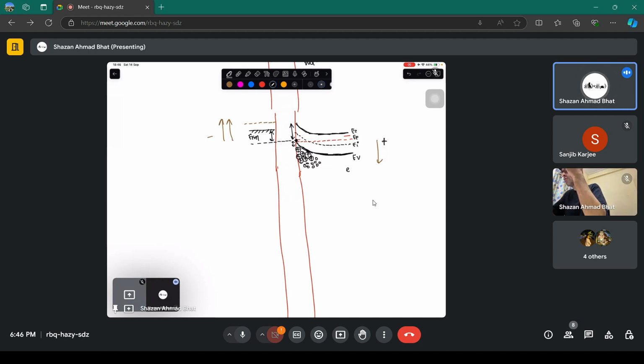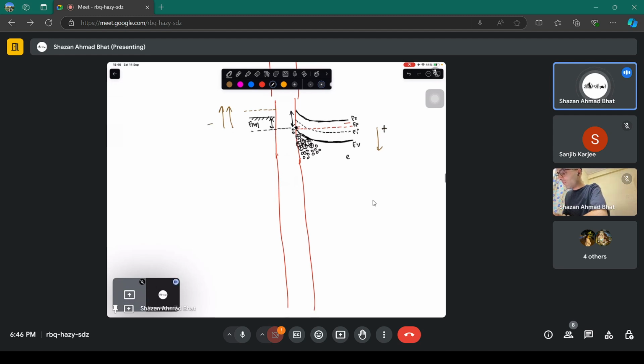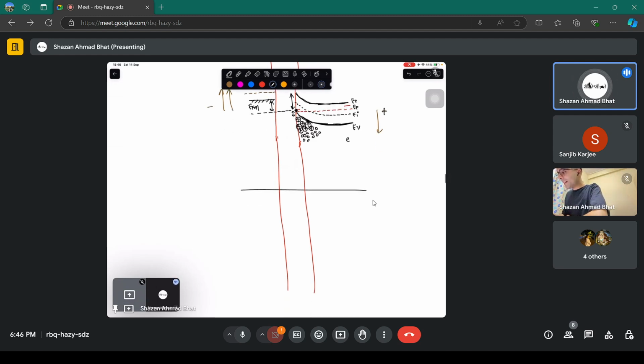So earlier you took those extra electrons. Now you are taking the electrons from the atoms themselves. So you are ionizing them more, and the remaining thing left is the holes, and they are the ones that are going to remain at this particular region. So now the holes are going to pile up at this region. Now you draw the space charge diagram again.